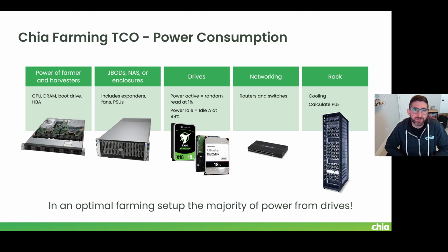If you're calculating power usage effectiveness, you basically would calculate the total power consumed by the IT equipment, and then you're taking the total power you're putting in, divided by the power of the IT equipment, and that gives you your power usage effectiveness. And so again, if you have this in a data center you're hosting yourself, the lights on the data center, the staff, the other cooling, all that stuff that is being used in the data center, that's part of this calculation.